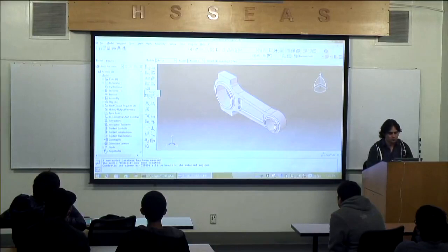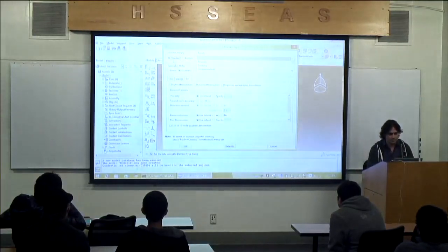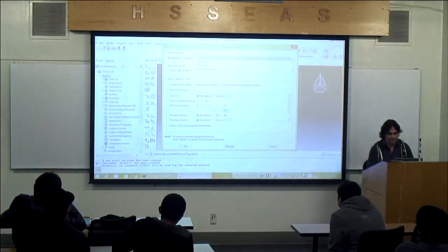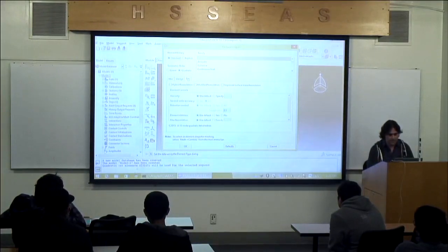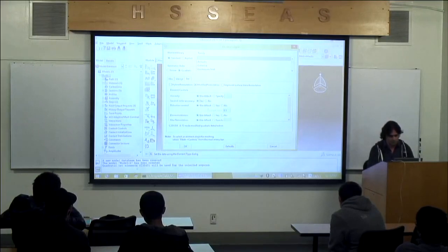Let's go to assign an element type to verify. So we're going to select a standard quadratic in the family 3D stress tetrahedron, and we're going to use a modified formulation. Just to improve, we're going to set a second order accuracy for this model. It's just some modification in the element type. So the element type is the one you can see at the bottom here. It's a 10-node modified quadratic tetrahedron. This is the element we're going to use.